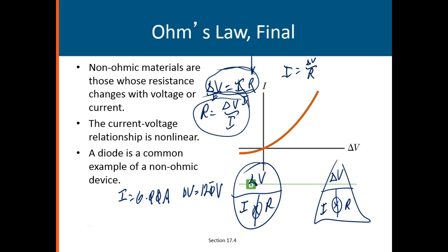That was the first illustration. The one we did last was I is equal to delta V over R. And the one we just did was R is equal to delta V over I. So if you like using this mnemonic device, you don't have to sit and divide by stuff like this, as long as you get them in the right order. Okay? And that's usually pretty easy to do. If they first gave it to you in this form, then whatever's on top goes on top, and whatever's on bottom goes at one of these two bottoms, and the other one goes at the other. So you can always set them up this way. And you'll find lots and lots of applications for this kind of procedure.